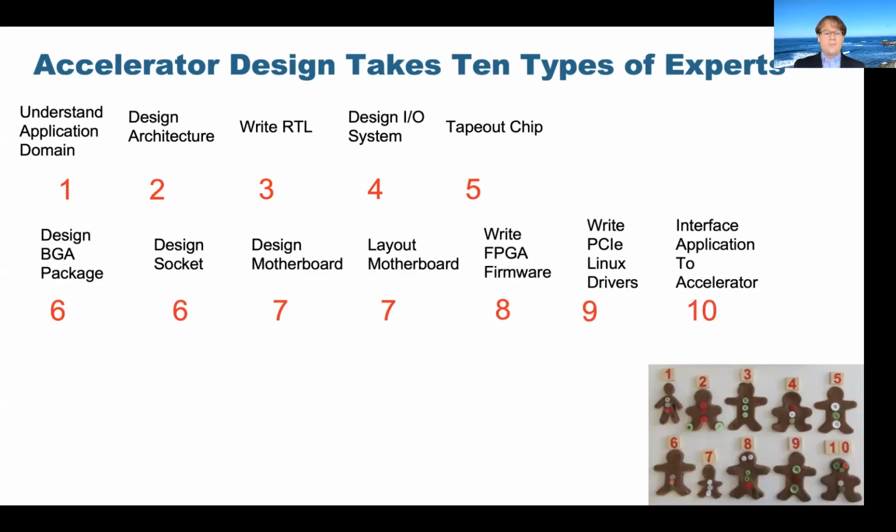But really, there are actually five more kinds of experts that you need. You need someone who knows packaging, someone who can specify the socket, someone who can design a motherboard, someone who can lay out a motherboard, someone who can write FPGA firmware, someone who can do PCIe Linux drivers, and finally someone who can interface the application to the accelerator. This would be someone modifying PyTorch to use the accelerator. That's a lot of experts to acquire just to execute an accelerator project.